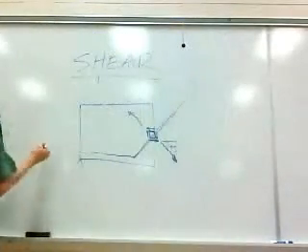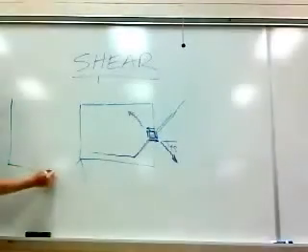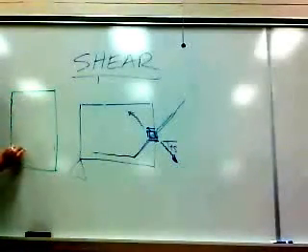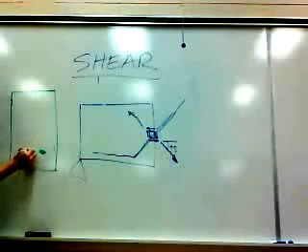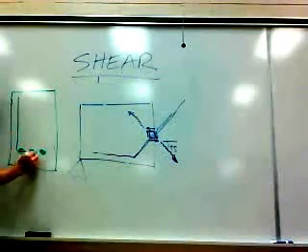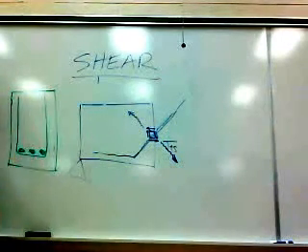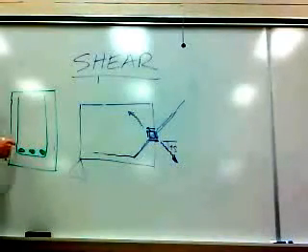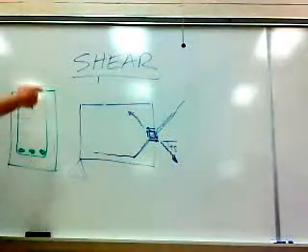Well, remember, we've already talked about this, but remember in our beam, the first couple of weeks we talked about this steel, the primary bending steel. But there's also this other steel that's going to be a U-shaped bar. It's called a stirrup. Well, that stirrup's going to occur at intervals.